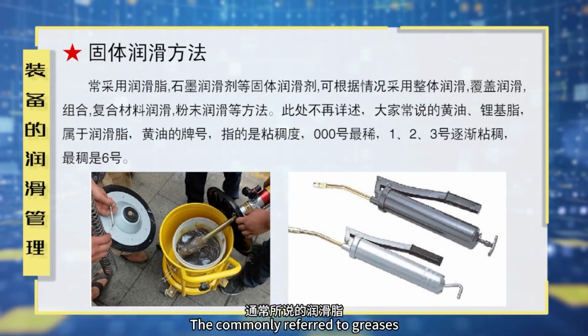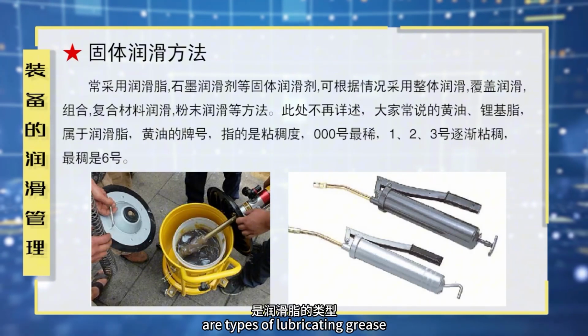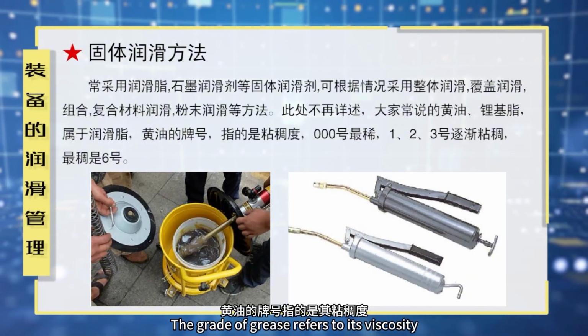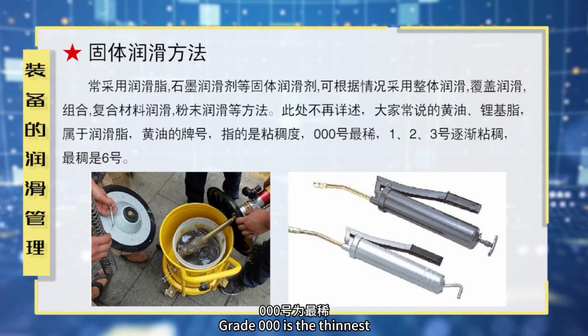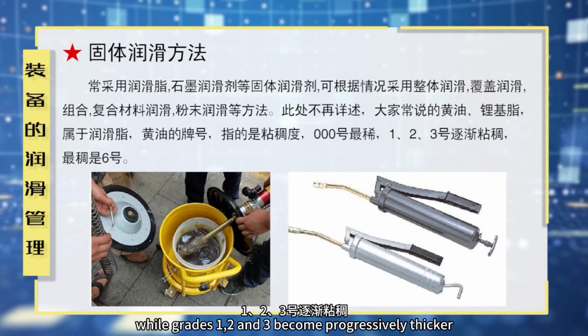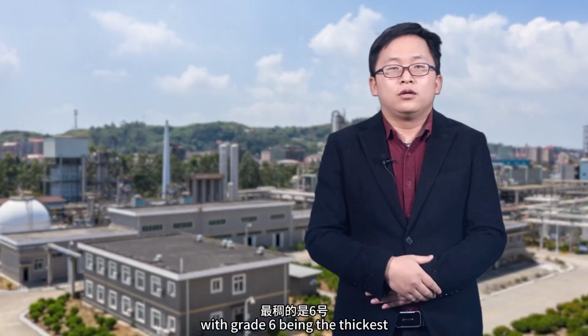The commonly referred to greases, such as butter and lithium-based grease, are types of lubricating grease. The grade of grease refers to its viscosity. Grade 000 is the thinnest, while grades 1, 2, and 3 become progressively thicker, with grade 6 being the thickest.